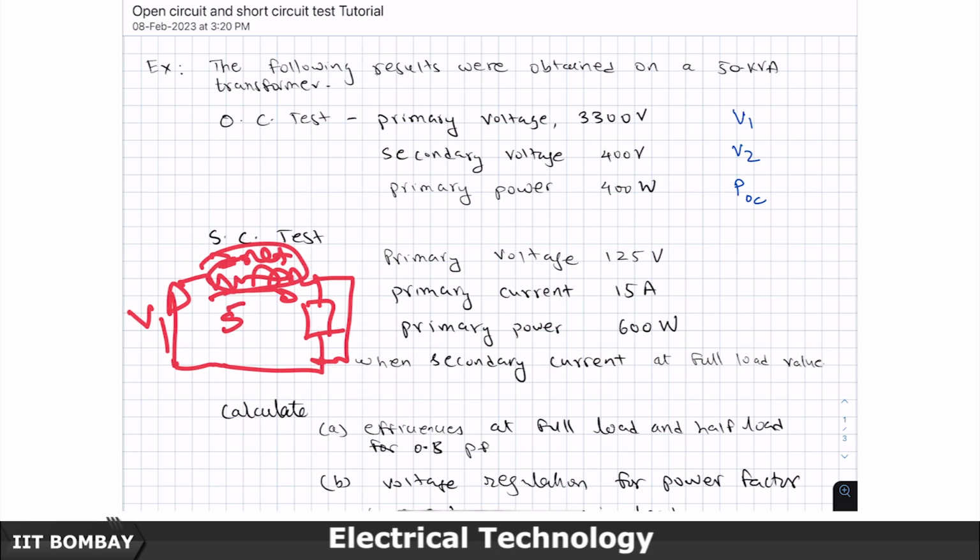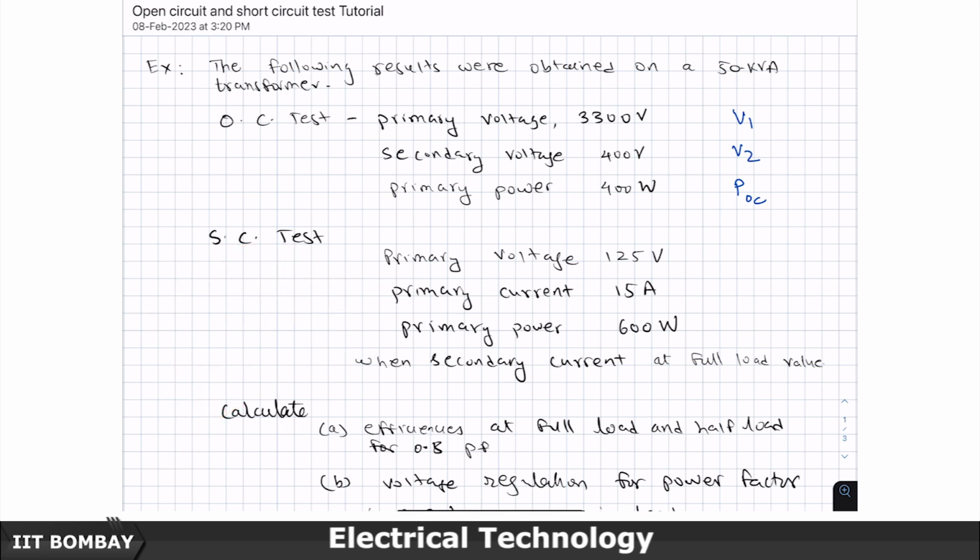You remember we say voltage regulation should be around a few percent. So, if this is 5%, then 95% is expended here. That means this impedance value is like 95:5, about 19 times the net leakage impedance of the transformer.